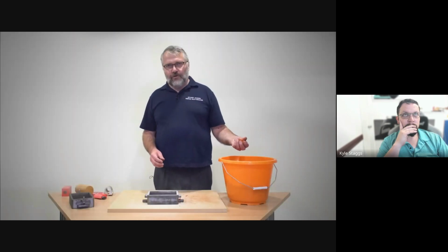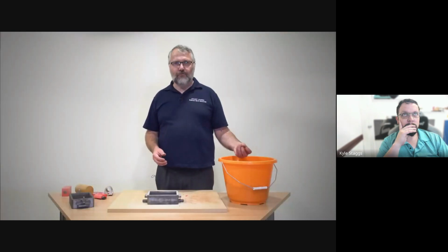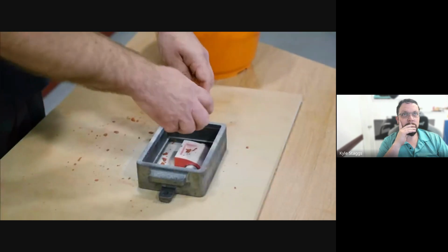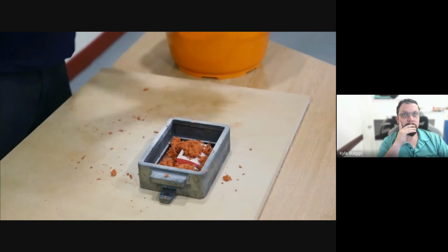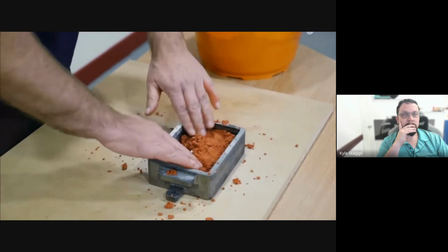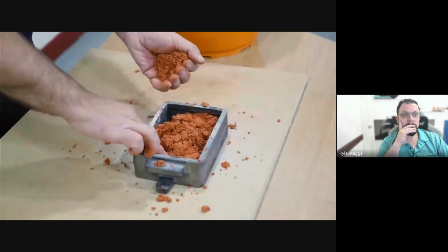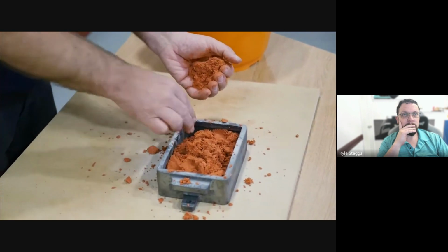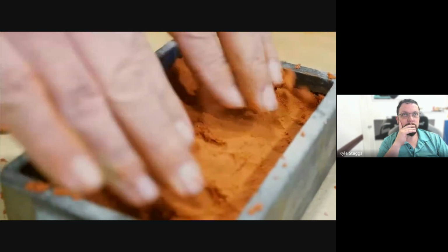Because the sand has oil, you may want to wear gloves to protect your hands or use a barrier cream, particularly if you're using reclaimed second-hand sand. We start off by sprinkling the sand, breaking it up as we go, just like making a rhubarb crumble topping. And we partly fill the box. We never fill it in one go. If you fill it in one go, you'll be able to form a very hard surface, but where you need the strength of the mould around the pattern will be compromised. So we just use our fingers to press the sand down to hold the pattern in place.